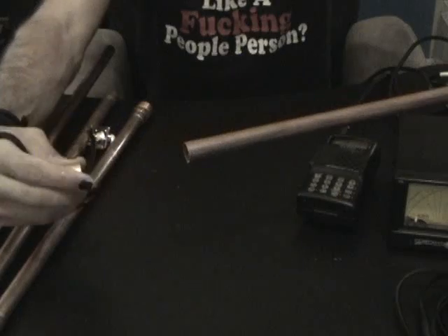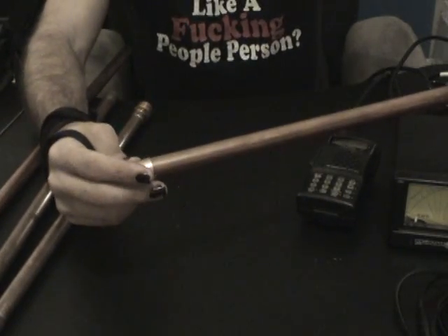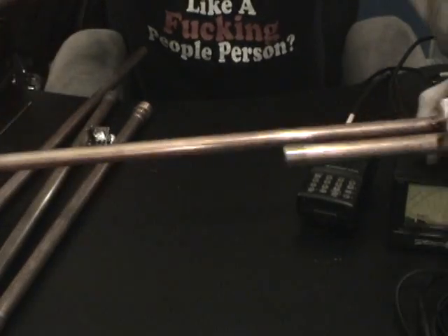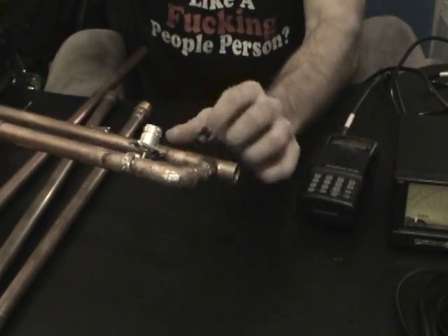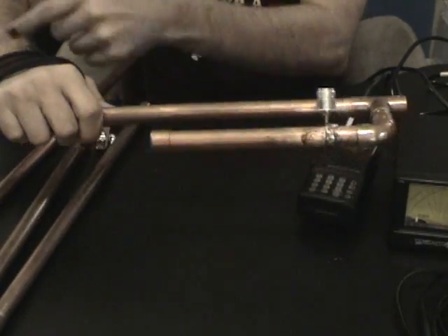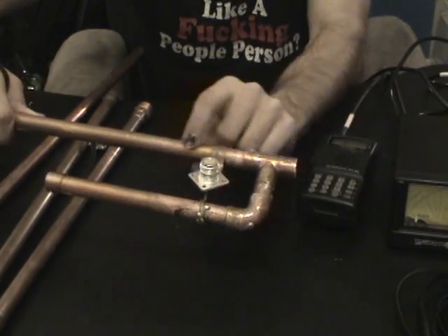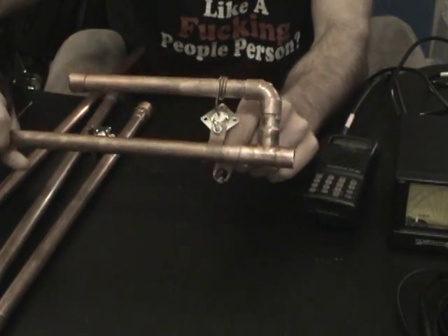I didn't actually solder these on. I didn't feel that this was a necessary step at this point, as these will not be put outdoors as of right now. Plus, if you actually want to adjust your SWR, you can shave down the ends and adjust your SWR. You can also adjust your SWR by actually moving this up and down the actual necks.